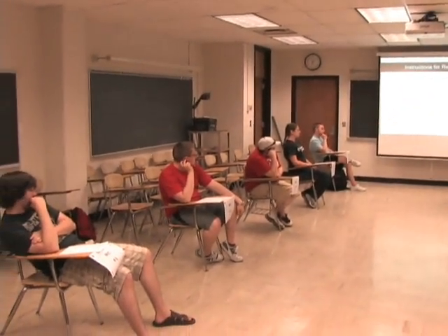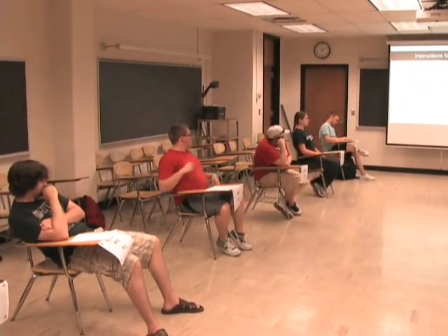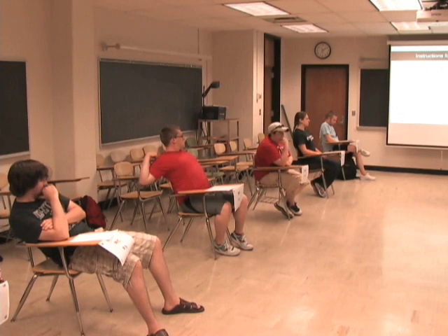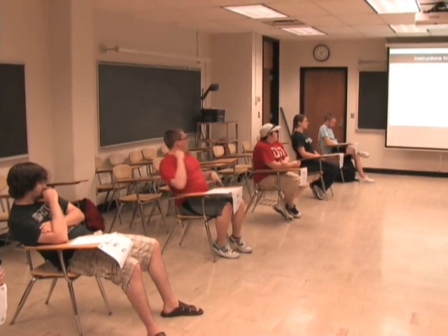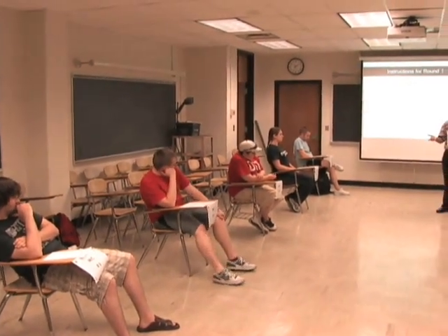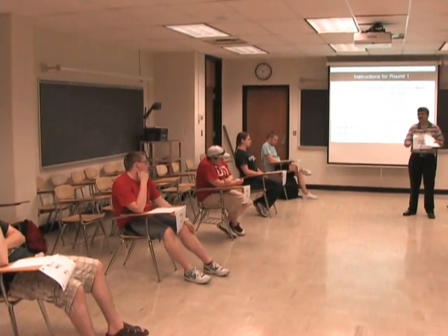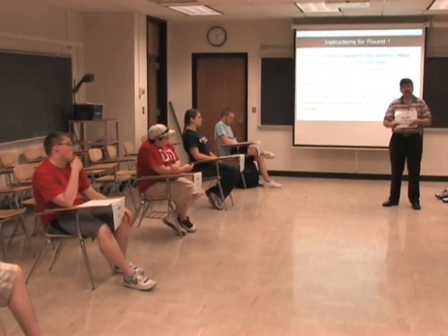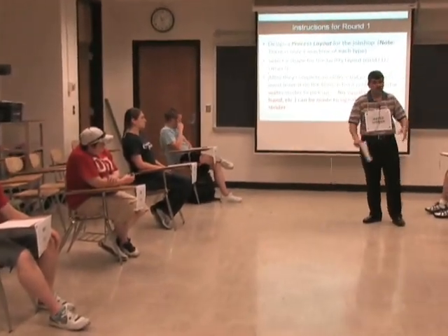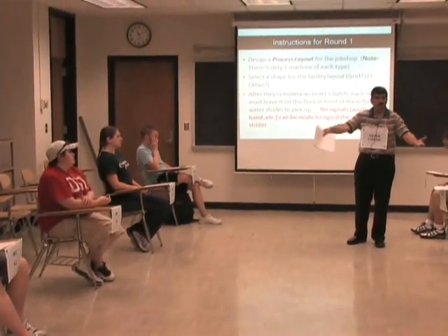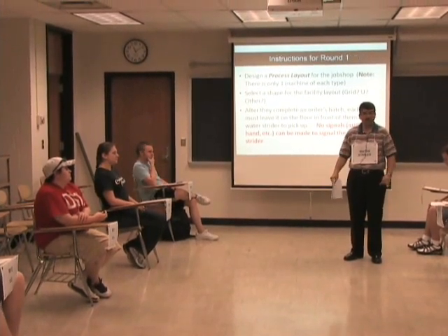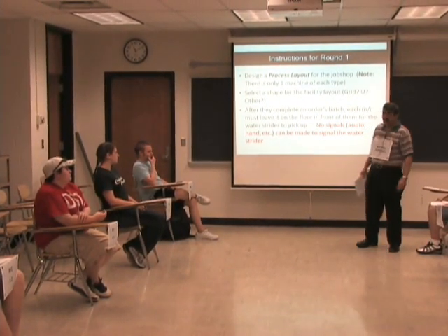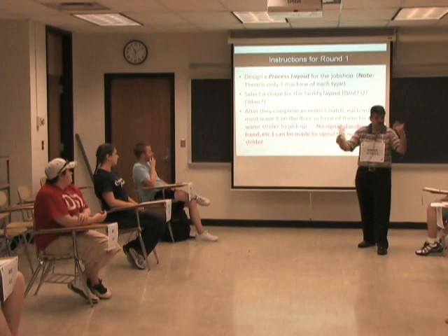Absolutely. So basically what you do is, you take the routings of all these parts, you have the lot size, so either manually or using something like FAST, you create the from-to chart. In this case, it's the Q type or the dollar type from-to chart, how much money is moving between them. Throw that from-to chart into Storm, arrange like a U-shaped grid, and something comes out. Okay. Then we select a shape. At this point, let's keep it U. Okay.